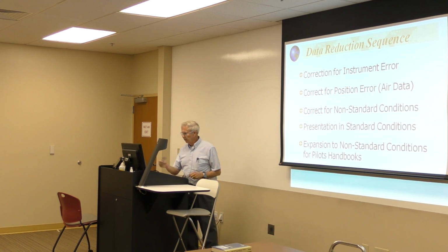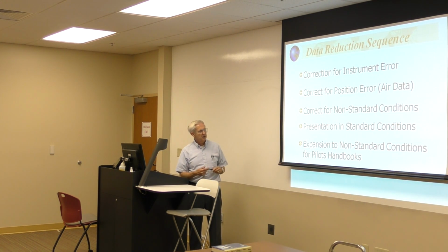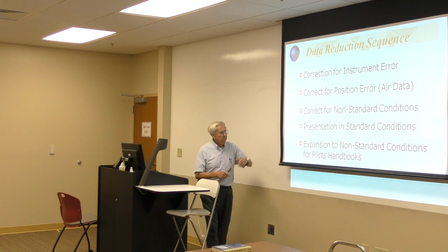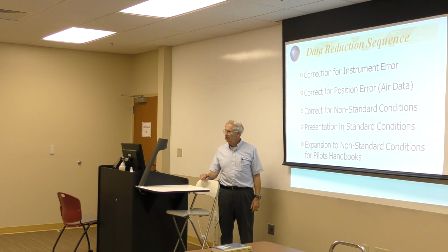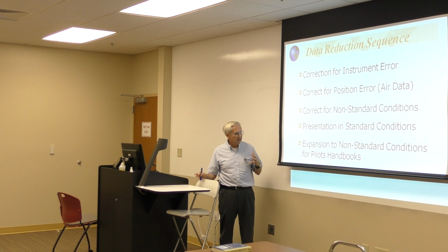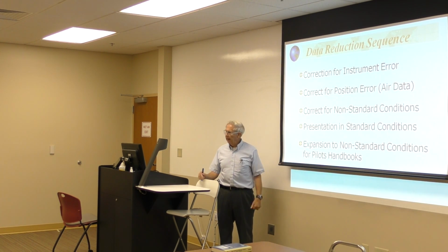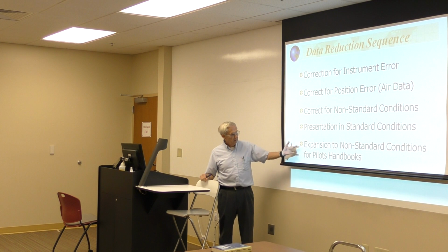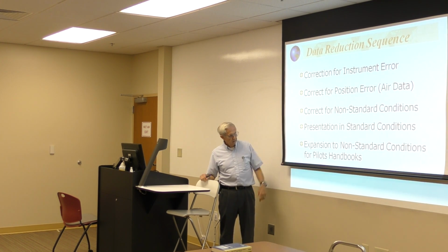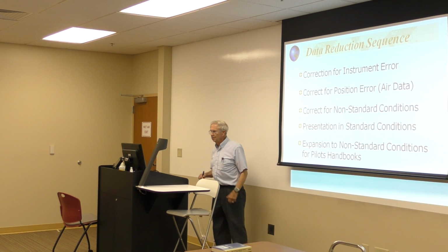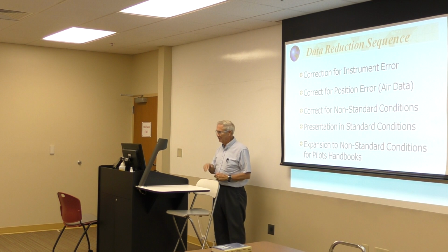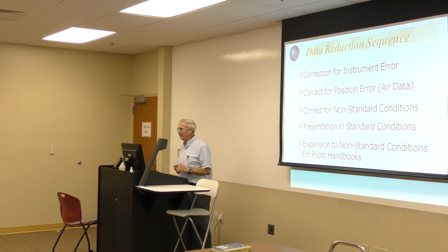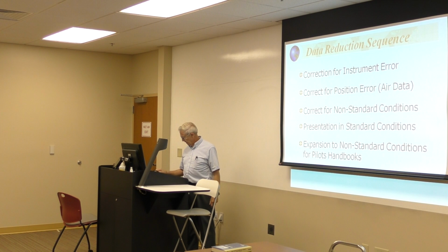Then we correct for non-standard conditions down to a standard day at sea level, and then we can make a presentation. We engineers like standard day sea level data. We can do something with that. Pilots don't understand that for the most part. So we have to expand it back to specified non-standard conditions for the pilot's handbook.